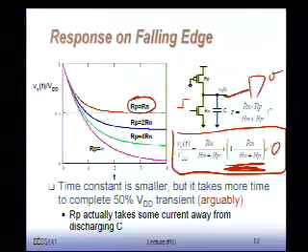If, however, I would look at the 50% point between 0 and VDD, you actually can see that making RP larger is a good idea. It makes you faster. If I actually make RP very small, or make them even equal, actually we'll never get to the 50% point. It's going to take an infinite amount of time. So we're going to get different values of the propagation delay depending on how we define the 50% point at the output. Okay? So both the arguments are right.